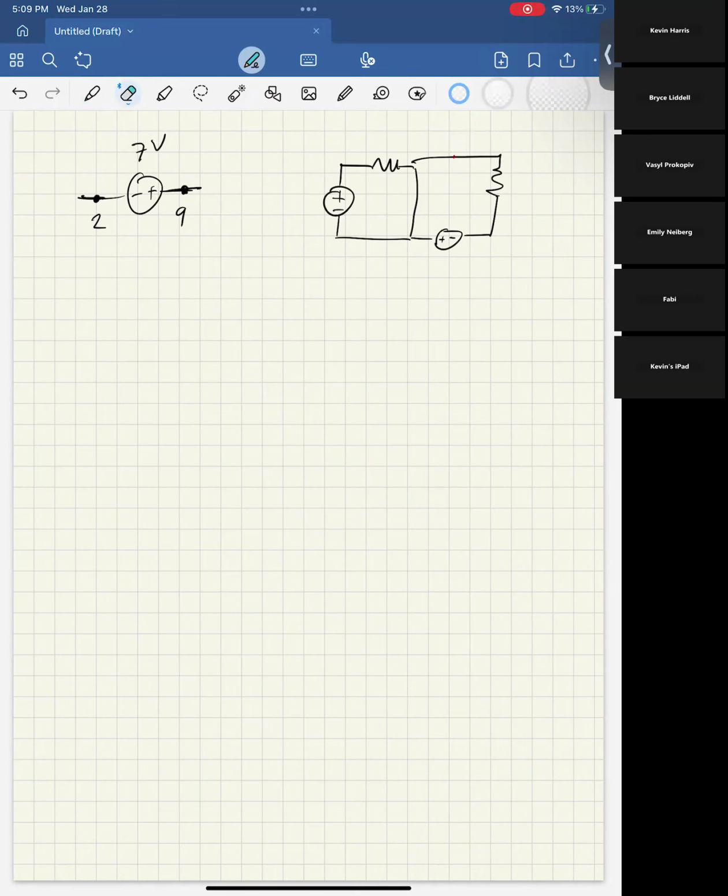What that means then is, this symbol means ground, or 0 volts. You can have a triangle or this thing. These are not quite the same, but they both mean 0 volts. You can use whatever you want. That means, though, if I then had a 2-volt source here and a 3-volt source here, even without doing anything else in this circuit, we can say, okay, we've defined this point as 0 volts. And now, if here I have 0 volts, and there's a difference of 2 volts between the sides, then here I would have negative 2 volts. And up here I would have 3 volts.